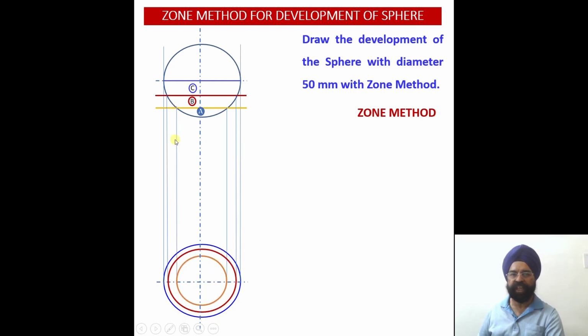And you see these projection lines, they are going to give me an indication. Corresponding to the first cutting plane, the divisions applicable will be on the greenish circle over here. Corresponding to the second cutting plane, the circle and the 12 divisions which will be applicable will be for the red color circle. And corresponding to this diameter portion, the third cutting plane, my outermost, that is the blue segments, will be required.